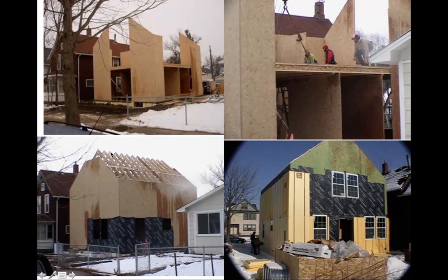So you have the loads coming down from the roof and from the snow load that's going to be supported by the column over this whole top length. Well, if you think about a fairly narrow column over this whole length, that's going to be much more difficult, and it's going to be a much too long a buckling distance.